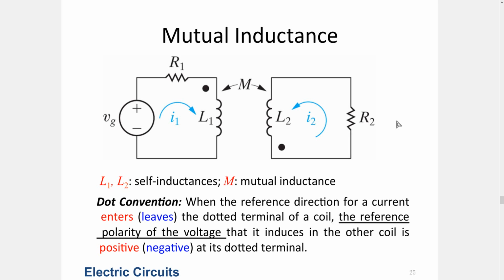And sometimes if you want to transfer the magnetic field, we use magnetic cores. These cores are built based on ferromagnetic materials that capture the magnetic flux and transfer it. Toroids and the iron cores that are used in transformers are such materials, so that we can control the coupling and the mutual inductance precisely.